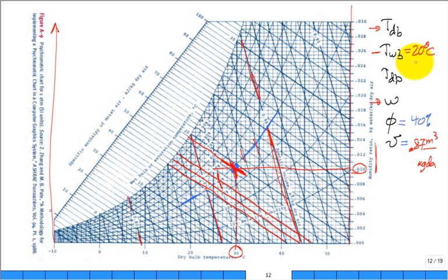All right, now I need to clean up the plot a little bit. Dew point. Can you get the dew point temperature for me? Exactly, just go like that. Conceptually, you cool it, and as you cool it, the humidity ratio doesn't change. It's going to stay the same.